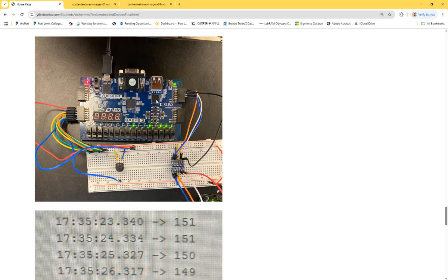And SPI communication is bidirectional. So eventually, the basic 3 board is gonna receive 5 volts logic, which is gonna damage it immediately. So you have to use a voltage shifter. It's a level shifter. That's converting all the digital signal from 3.3 volts to 5 volts and from 5 volts to 3.3 volts. So you need a little level shifter in the middle.